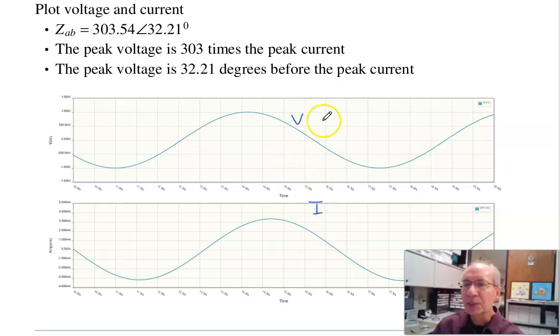And remember Eli the Iceman? That's ELI. Here voltage comes before current, so this is an inductive load. The phase shift is positive. The voltage I can pull off in phasor form. This is the peak. The input is 1 volt. Where's t equals 0? Okay, let's just arbitrarily call this t equals 0. The phase is 0 degrees. The current, here's the peak.